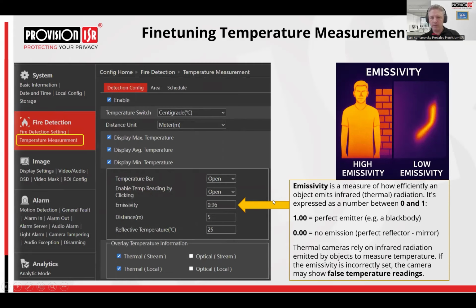So when we're talking about our interface of the thermal camera, you see here there is a temperature measurement. This is another tool for us to use the thermal camera, so we can detect some kind of temperature anomalies. When we are working with this interface, we see different parameters, and one of them is emissivity. This is usually the number used for the environment, similar to human skin. And we can define for the camera how far it is from the object it's measuring. So there is some distance from the camera to the object, and it reflects the average temperature in the surrounding of this specific environment.